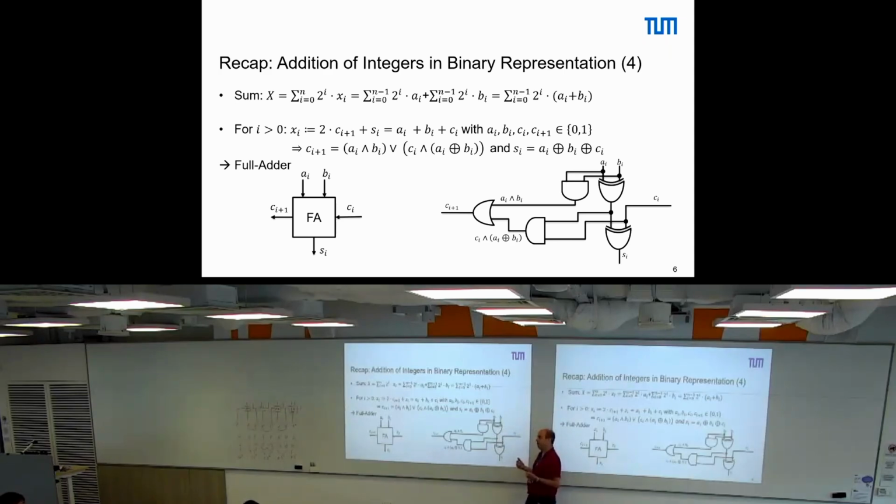If you consider the wires in between, yes, but I would consider this negligible. Yes. So switching a gate means that for a short time we have a short current from VDD to ground, we have dynamic power consumption.